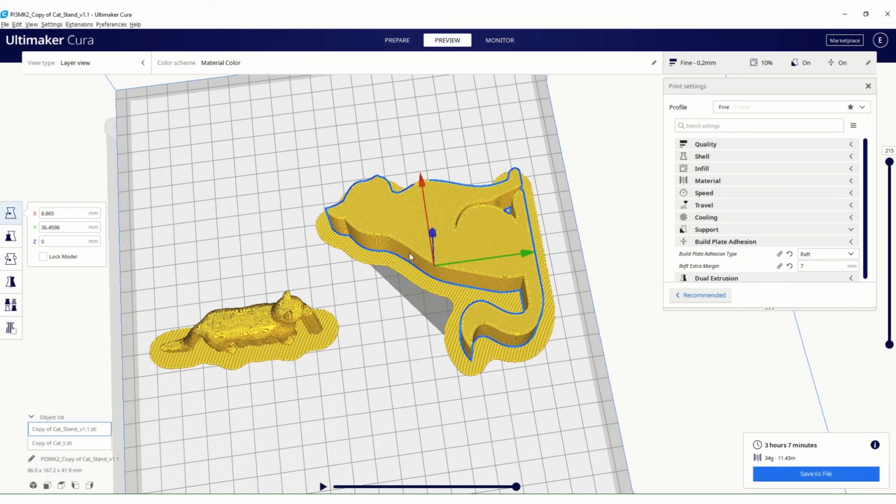The reason you would want a larger raft from your model, like that 15 millimeter one, is if you are printing something really big, like it has a wide bottom. What can happen is as the nozzle is going all the way around, the filament cools off so much that it starts to peel back when it gets the second layer on it, because the layer is hot. And when that layer starts to cool, it actually starts to contract and pull. So the corners come up. So if you make your raft a lot wider, it can help to keep it down and attached to the build plate.